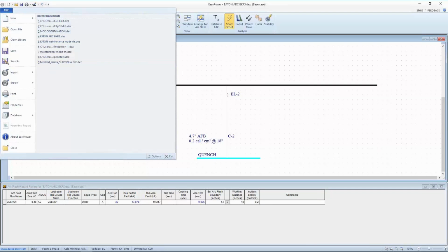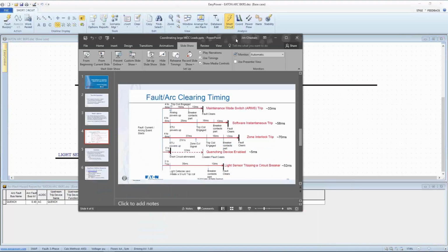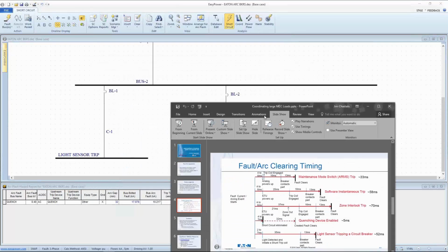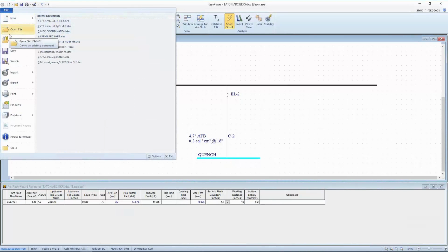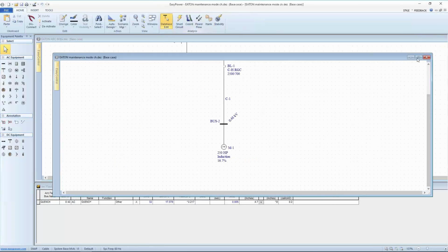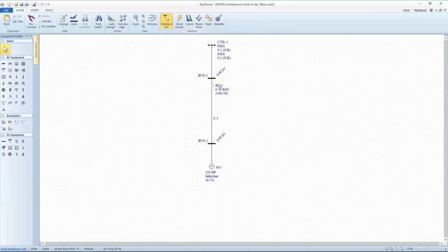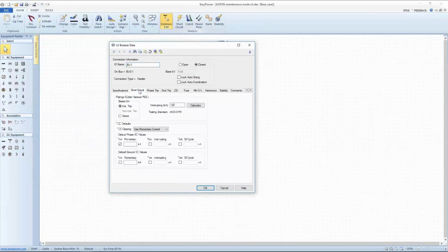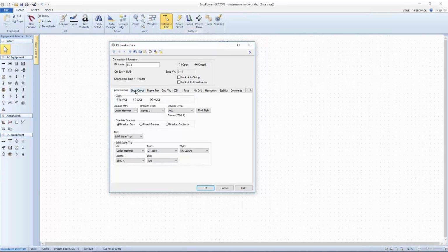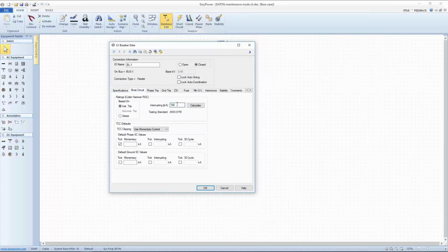All right, then the third element. The other element that I want to show is maintenance mode, and this is a feature that's been in several manufacturers' feature sets for low voltage power circuit breakers. Where it is set up, or where it's in the data sheet, is once we've described the manufacturer and the trip unit, we verify that it's in the database. These numbers will usually start off with 0 when I put together a part number, and by clicking calculate, the fact that it changes the number here tells me I found this part number in the database, and the manufacturer guarantees it to work to an interrupt rating of 100,000 amps, and the testing standard is ANSI symmetrical current.